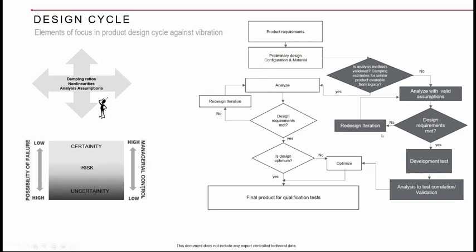The gray items are what you have traditionally focused on when your vibration problem is severe. Like, are analysis methods validated? Are damping estimates for similar products available from legacy? So it is always important for us to understand whether I have feature-based data or product-level data for the damping, and for the boundary conditions as well. Like I said, a ball joint or a spherical joint or a kind of kinematic coupling. How do I model it at lower excitations, at higher excitations, when the preload is present, when certain friction is present? It may not be simply freely rotating, right?